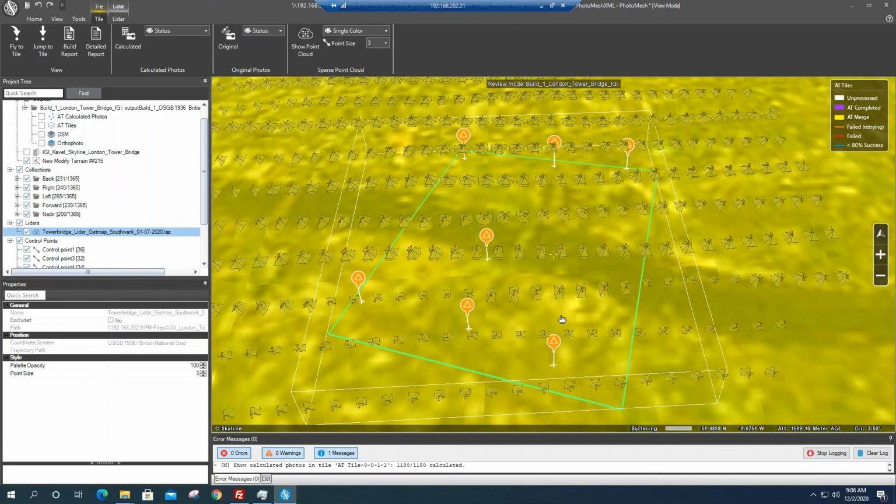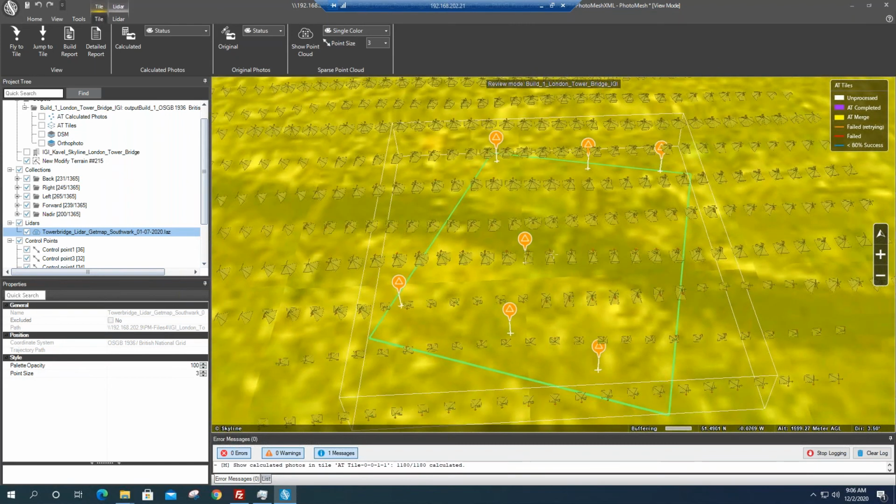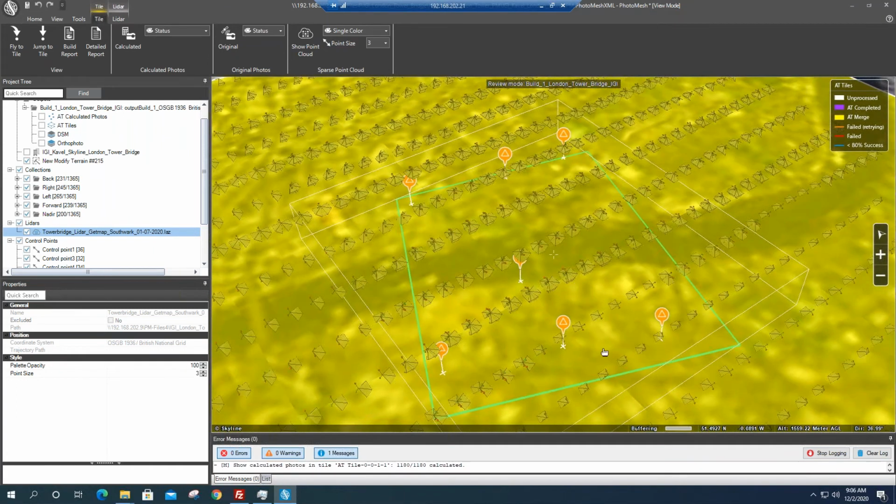Those are things that get done as part of the bundle adjustment, but in terms of getting to a corrected aerial GPS or input exterior orientation, that's usually done in the camera post-processing and image post-processing after the flight. If there is control, we have very advanced and robust capabilities to minimize any errors and achieve a very high accuracy result, which we'll review as well.